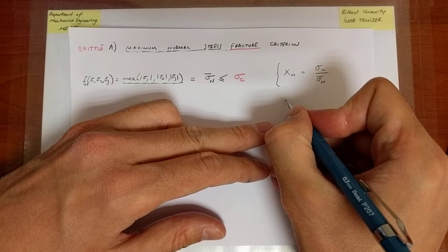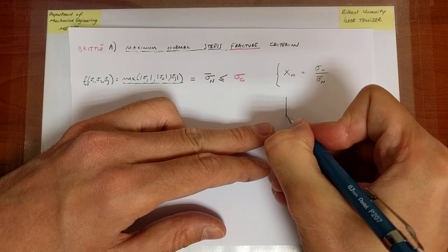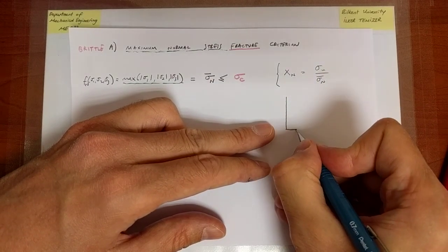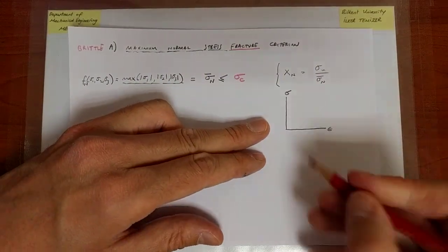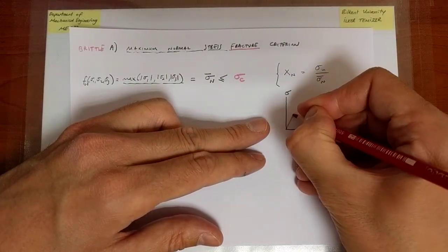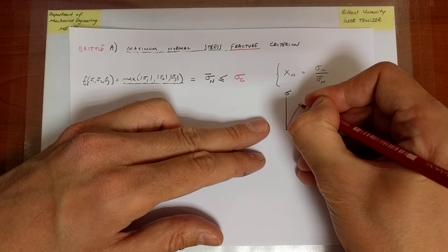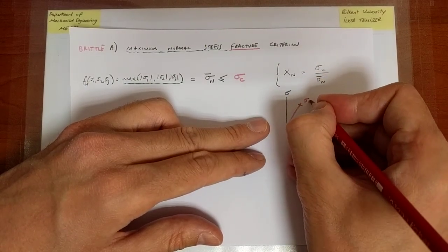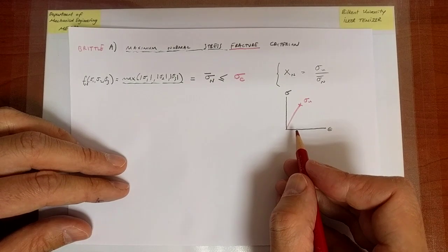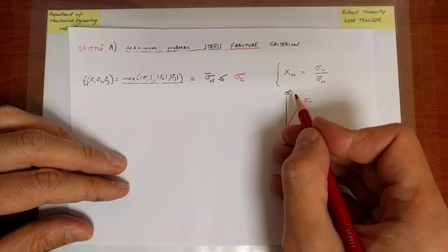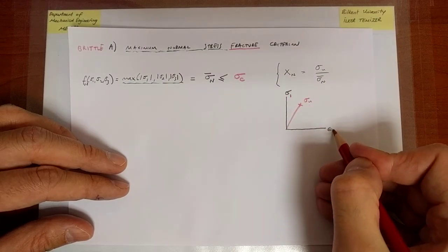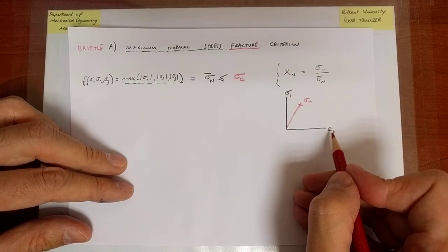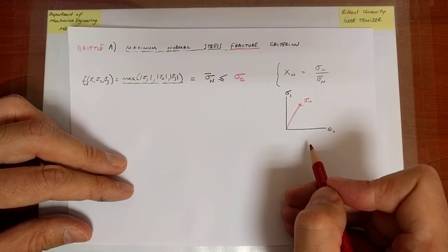And the way I will deduce it is to always fall back on the idea that the critical value comes from a uniaxial tension test. And in a uniaxial tension test, if I pull, the material is ultimately going to fail at a point which is equal to sigma u, the ultimate strength of the material. And in this case, there is only one stress. Let's call that sigma 1 if you like. And therefore, the corresponding strain is a principal strain, which is epsilon 1.